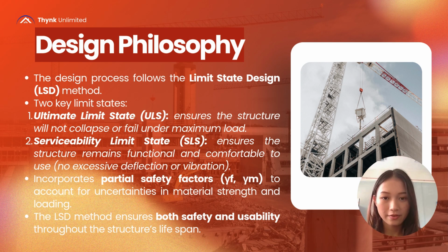Next is the design philosophy. The design process follows the limit state design (LSD) method. There are two key limit states. First one is ultimate limit state (ULS) that ensures the structure will not collapse or fail under maximum load. Second one is serviceability limit state (SLS).